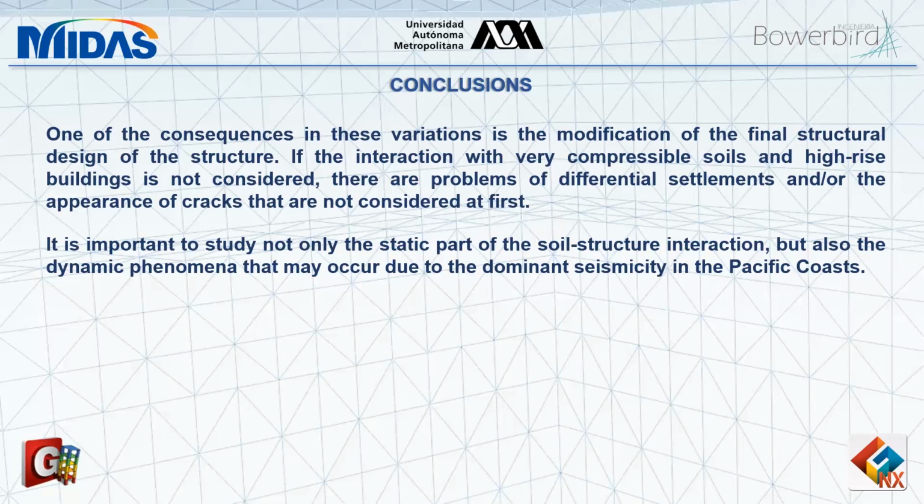And so we see that, of course, there's a lot of theory behind the constitutive models, but the Mohr-Coulomb failure or constitutive model is pretty well understood and pretty well accepted. I would say close to 70 to 75% of the cases in 3D geotech finite element software use Mohr-Coulomb to capture softer soils, compressible soils. And so this is a pretty handy tool. It's not too much beyond what the input values would be.